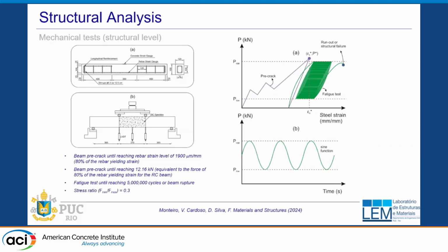Of course, the next step is to go through a full-scale test. It's a small model test, but now you have a rebar in the middle four-point bending zone. We have no shear reinforcement provided, so that the probability of failure of the sample in the constant moment region of the beam is very small. So now we can focus on this area, and start doing a few cycles to get ourselves to a pre-crack zone. Once it's cracked, at that point, you just go up to